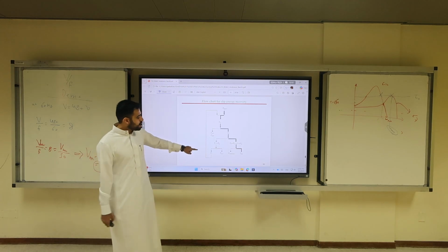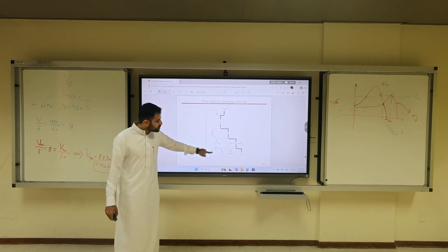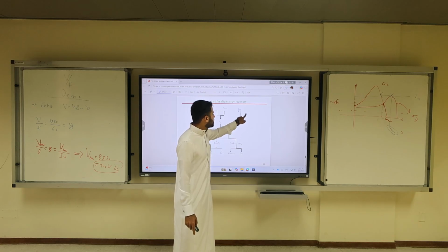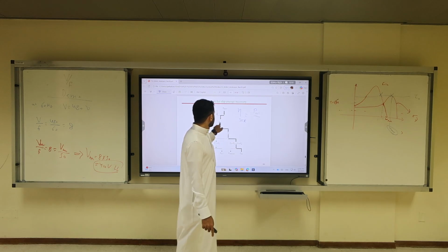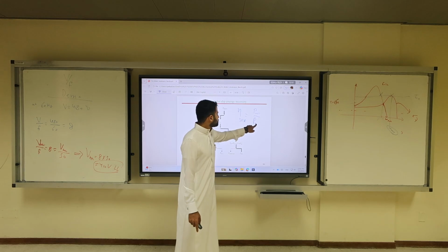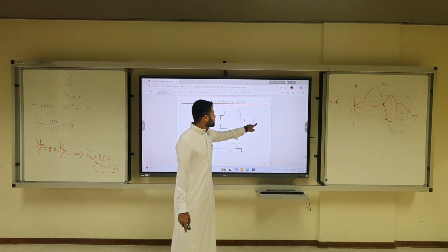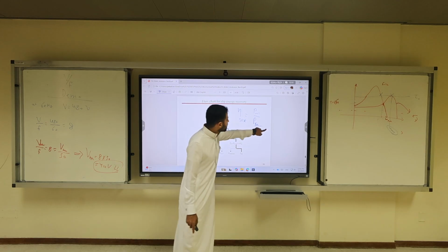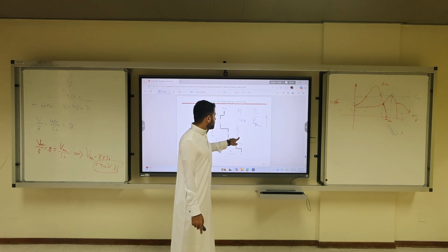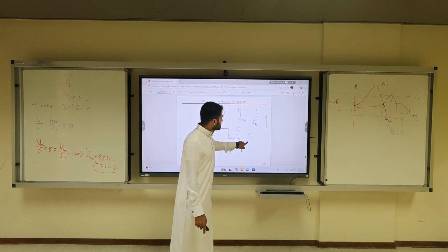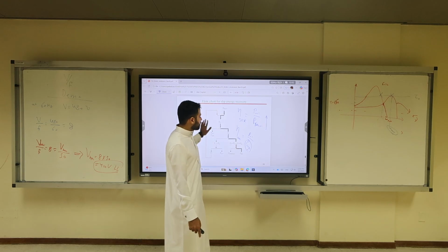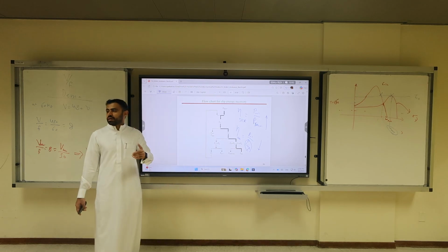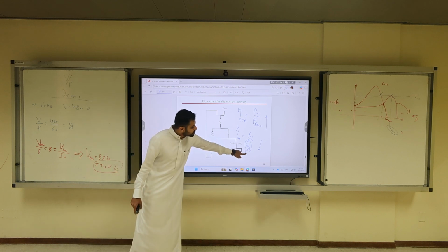Now, what is the energy recovery? You recover the copper losses, some of it, not all of it, and you retrieve it back to your inputs. So your efficiency for slip energy recovery is P output over P source. Is P source with slip energy larger or smaller? It's smaller. So you get higher efficiency. Eta for non-slip energy recovery is P output over P supply. Is P supply without slip energy recovery larger or smaller? It is larger. So your efficiency would be smaller. You divide by a larger number. P source here is larger.